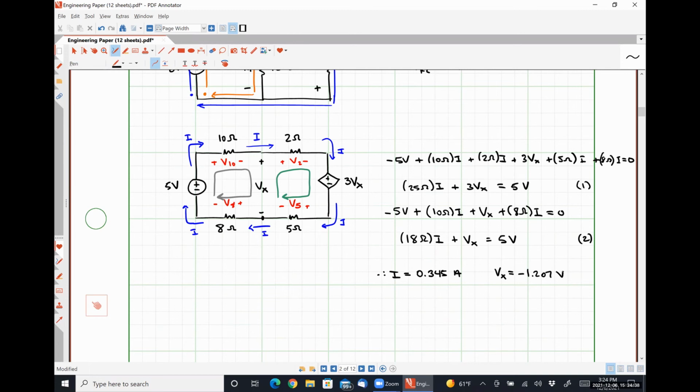So another thing that I can say pretty definitively here is that anytime we have a single loop circuit where all of the elements are connected in series, Kirchhoff's voltage law should be where you start your analysis, okay? That's usually going to be one of the easiest ways to analyze the circuit. And it's because there's a common current flowing through everything, so that you should be able to figure out pretty easily. All right. Any questions regarding Kirchhoff's voltage law and its application in this example that we used here?